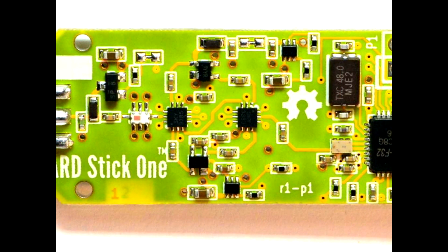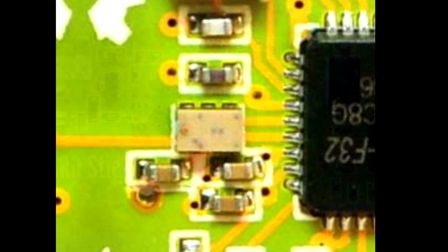So what's the first thing you see over near the radio chip? This. That's a balun. Again, I used a monolithic transformer, a single component, instead of a mess of capacitors and inductors. Now, one of the magic things about Yardstick 1 is that balun, and the only reason I knew about it was because I found it when I did the HackRF project.